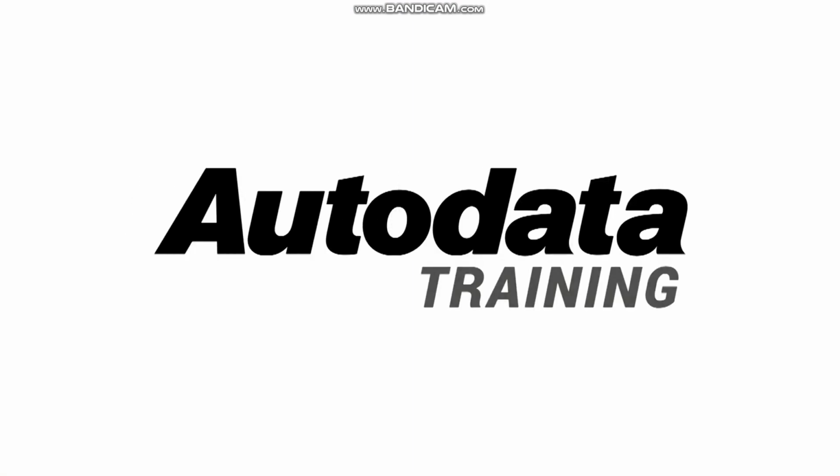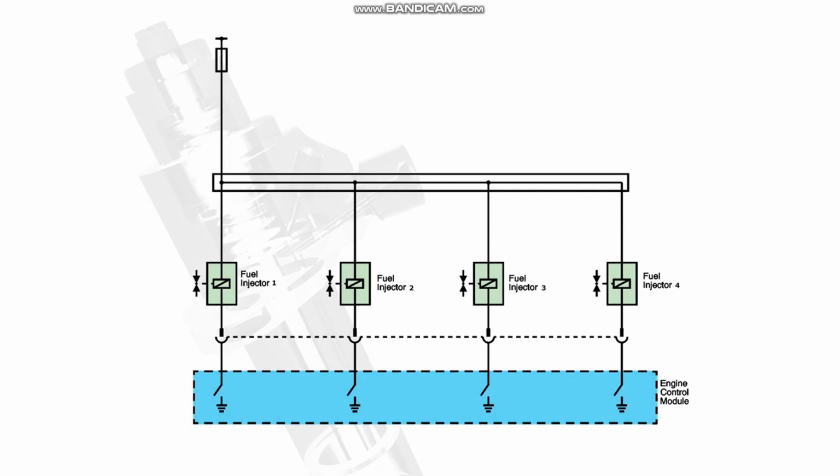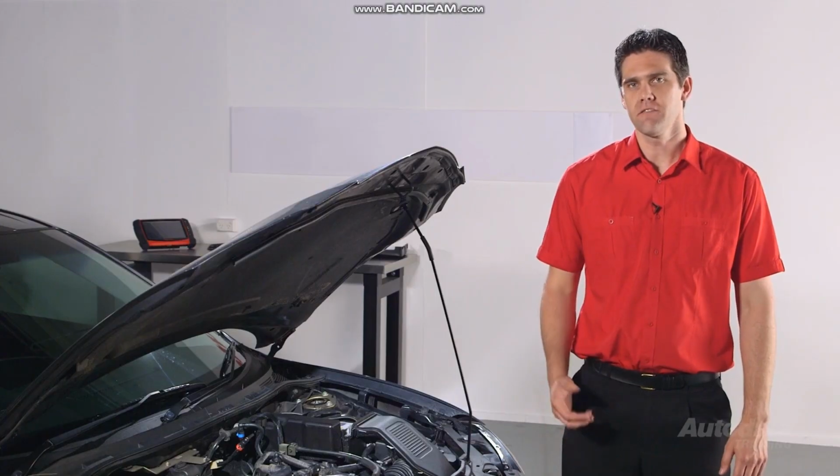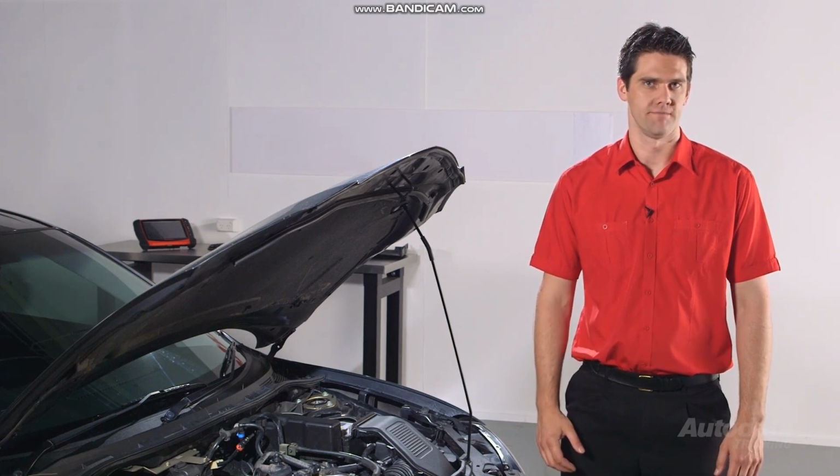In this video, I'm covering the codes for fuel injector voltage high. This DTC will set when the engine control module, or ECM, has detected a high voltage in the control side of the circuit. There will be individual codes for each cylinder, from 1 to 12.